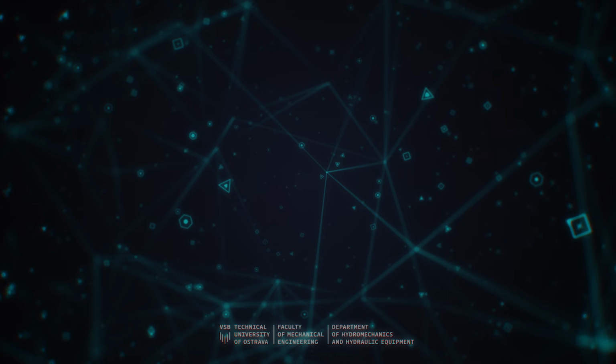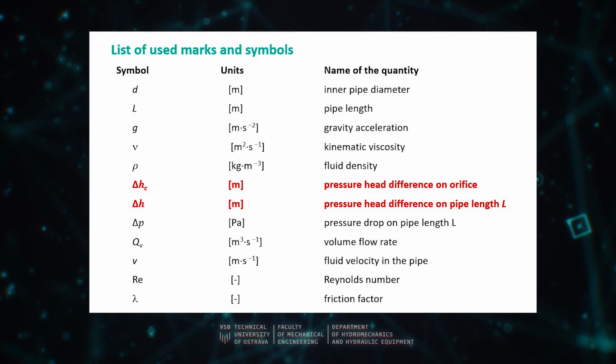Measurement evaluation. The known variables are the internal diameter, pipe length, and gravity acceleration. The density and kinematic viscosity of water are determined on the basis of laboratory conditions. The measured values are the loss heights on the orifice and on the straight section of a specific pipe. The calculated variables are volume flow, the water velocity in the pipeline, the Reynolds number, pressure drop, and friction coefficient lambda.